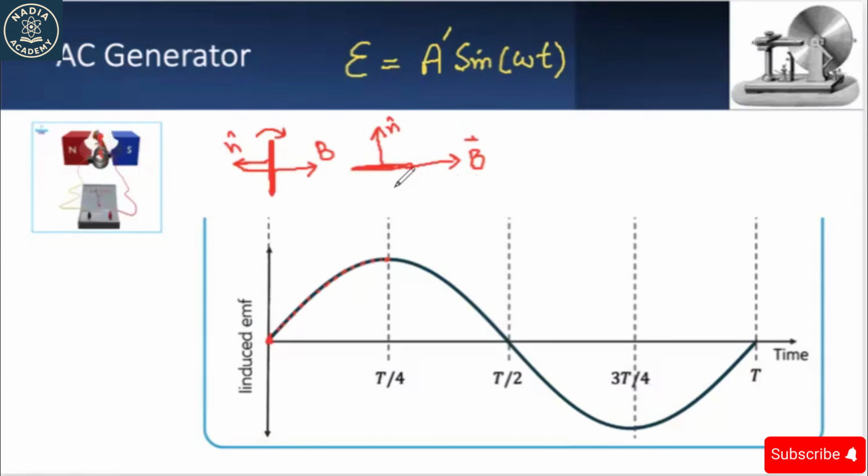So in this situation, the induced EMF, which is at the top here, will start to decrease with a further decrease of the angle, because I am considering here that it is 180 degrees and here it is 90 degrees. Then it will again be moving toward 0, as the magnetic flux starts to link with the coil. So now your flux is increasing as a function of time.